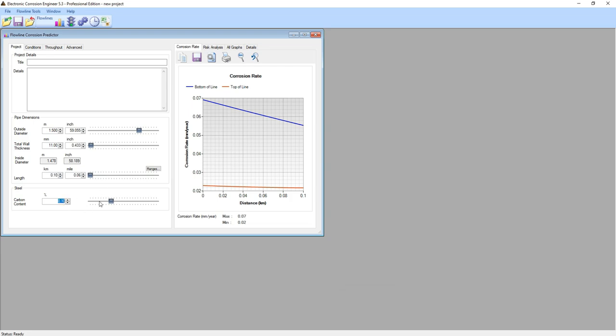As you may notice, since this module is generated for pipe corrosion estimation, the software automatically changed the length to 100 meter. This is not too important in our current case. We are using the software just to understand the tendency of carbon steel to be corroded in contact with the process gas. Finally, the carbon content of the pressure vessel, which is limited to 0.23% in wet sour services.